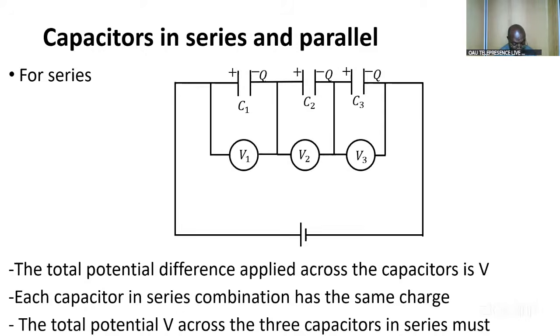You have Q all over C1. And I've said the other one will be Q all over C2, because their charge are the same. So the first one, Q all over C1, will give us 667 volts. The other one you just subtract from 1000, and that will be 333. Very good. Note the 333. Yeah, 333. You are right. I could see some of you are getting it. That's okay. 333. Thank you very much.